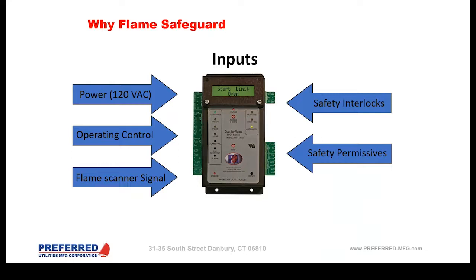So Steve, just to add to your inputs point there: if you lose the signal from your operating input, you don't trip the burner, you just shut down the burner because you have no load. Whether it's high steam pressure or operating steam pressure, operating hot water. And I guess sometimes the first water level shutdown can be in the operating limit as well. That's exactly correct. Absolutely. That way, when the water is made up and we get above that first low water, it will go ahead and allow the burner to restart.